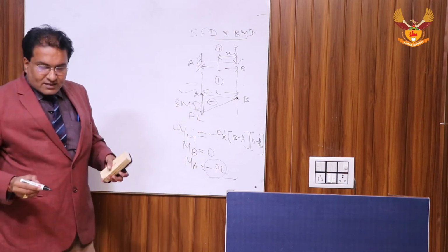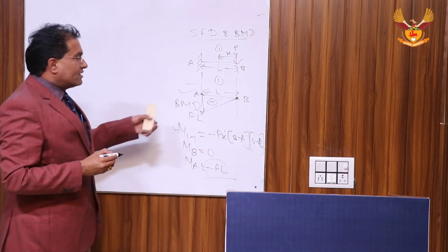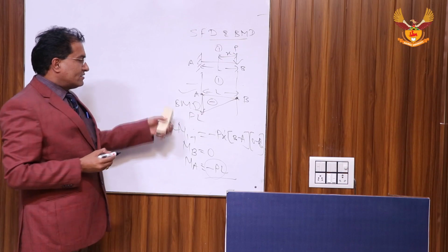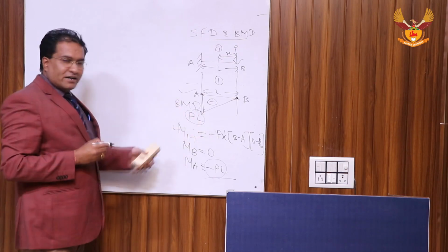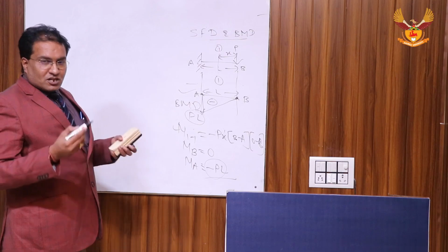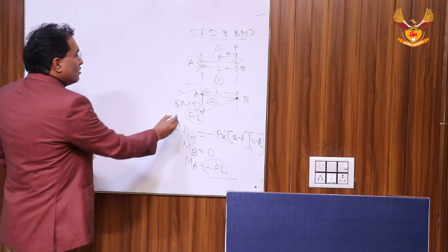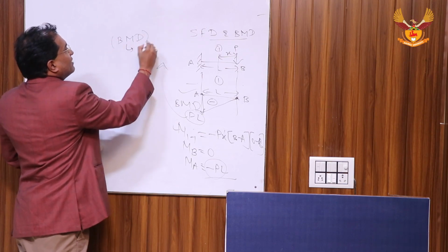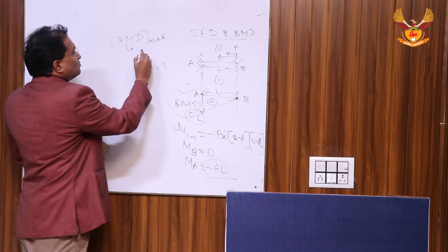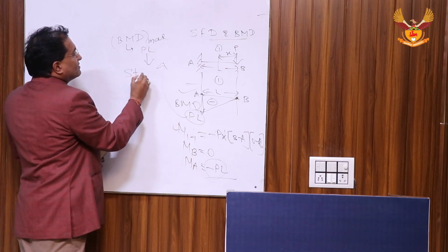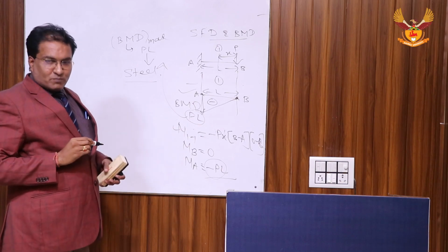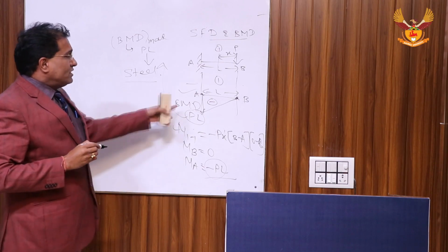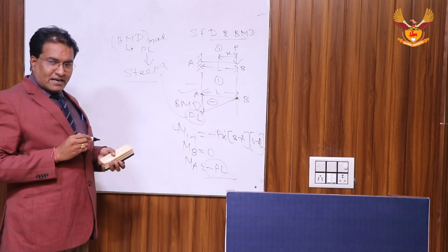Basically, when we plot these shear force diagram and bending moment diagrams, they are very helpful in designing of the structures. For example, we are getting the value of bending moment PL. In actual structure, when we are designing cantilever beam, we have to take this value of bending moment diagram. Maximum value from this bending moment diagram is PL, and then we have to design steel reinforcement. So for providing steel reinforcement in beam, we have to plot first of all the bending moment diagram.